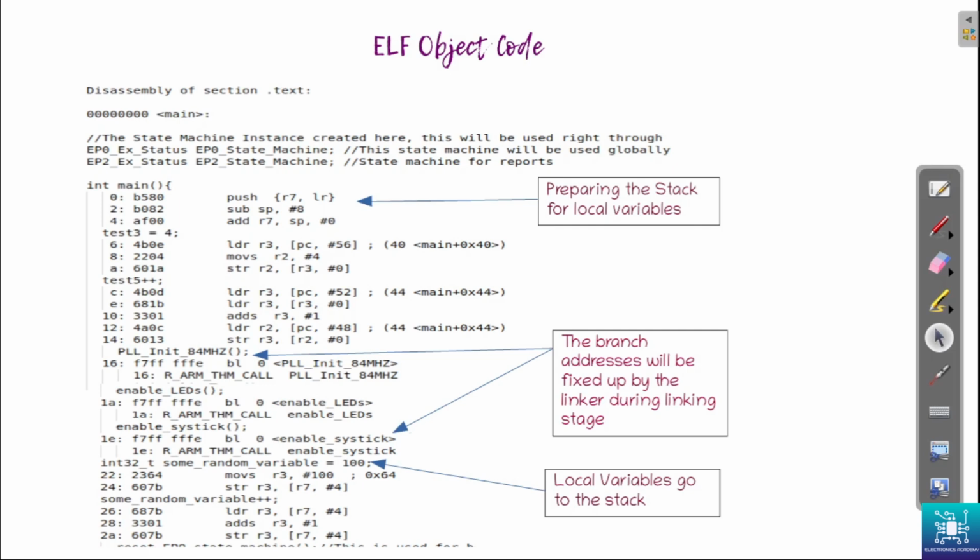When you pass code into the compiler, as we said, it creates a .text section where it holds the code. Now we have asked for a disassembly view here for the code, and that is the reason we are seeing the disassembly view. That is, we have the actual instruction and the breakdown of that instruction into assembly and machine language as well. Okay, so this is the assembly.